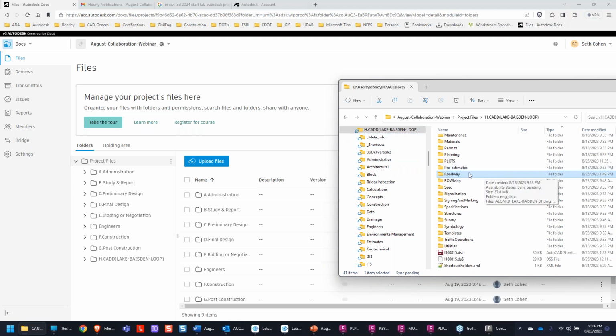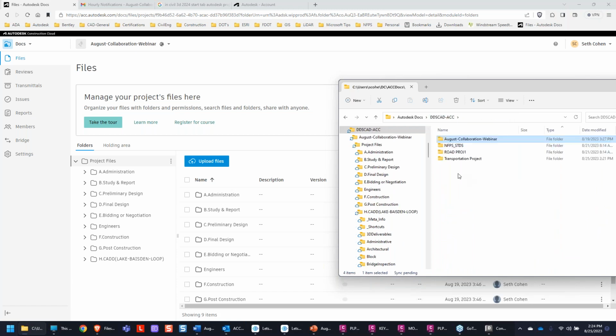Okay. All right, now for me as a CAD manager, someone who manages it, for many companies, you want to know how to manage your CAD standards, because when someone goes to plot, or XREF, or where's your temp folder, all this kind of stuff. My CUI, maybe you have an enterprise CUI. How do you manage that? And this is how you manage it, in my opinion. This is the best way to do it, okay? What I do, and I'm the only one as the CAD manager with permissions, everyone can see it, but I'm the only one with permissions.